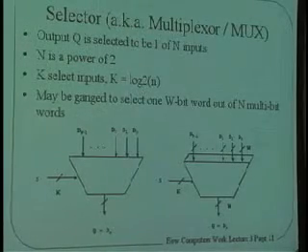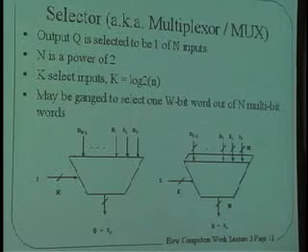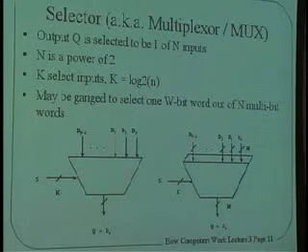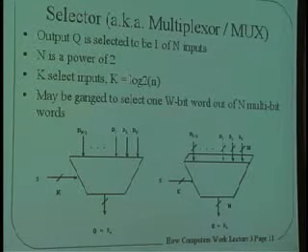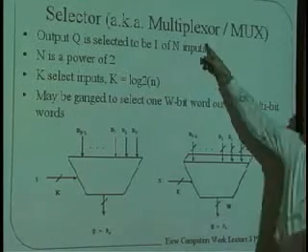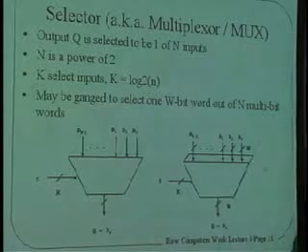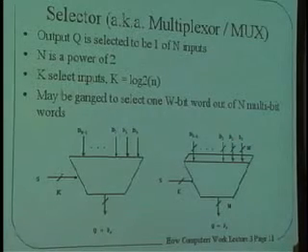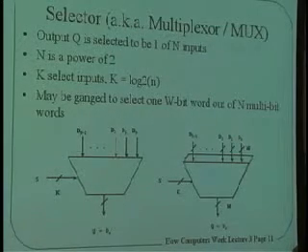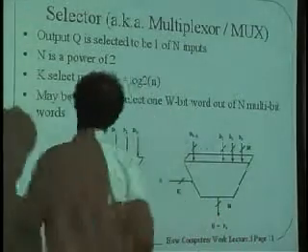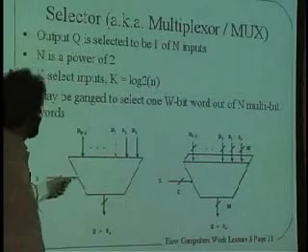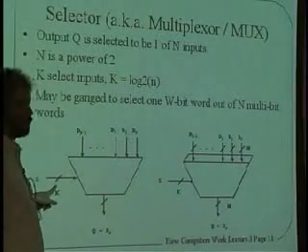So that was the hardest thing to get through, if you understand how the registers work. Let's take a look at the easier things. These selectors, also called multiplexers or muxes, are used for choosing one of n different inputs for a particular output. The way they choose it is based upon a select control, S, that comes in. And this may have several bits to it.